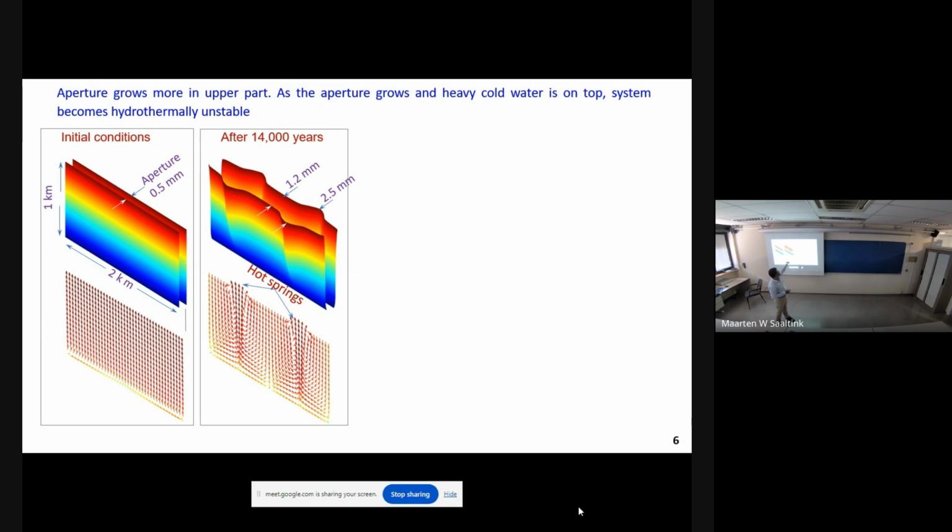If the temperature diffusion happens, then it is delayed instability, and the Rayleigh number required will be much smaller. The other one, if you don't allow the temperature to dissipate or exchange, is called instantaneous. Then it will happen immediately, but it requires a very high Rayleigh number.